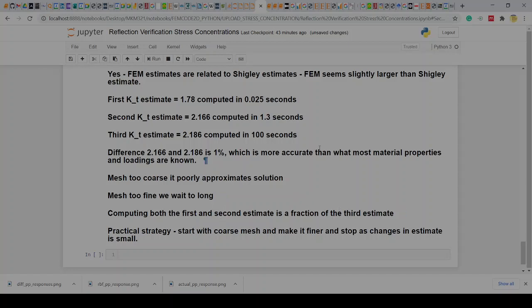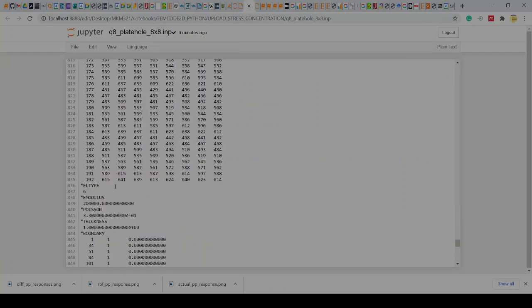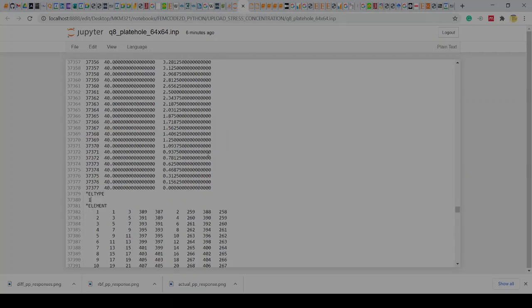Just out of curiosity, I'm going to rerun these, but on purpose make them now sort of a plane strain condition. I'm just going to do this to show you more or less what the effect is of the way we model this 2D problem. Okay, so this is now going to be a plane strain scenario that we're going to be modeling here.